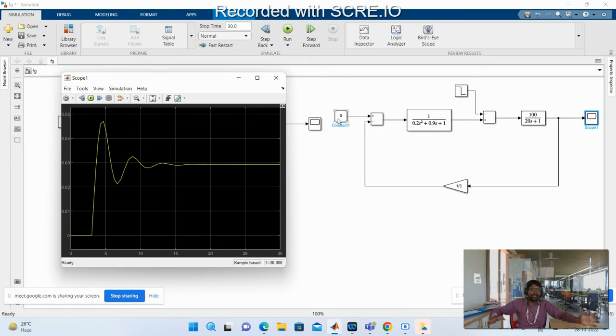The steam valve will be opened, more steam will go, then the generator speed will go up, and frequency increases and reaches the nominal value. So you have to control the speed changer position in such a way that even if the load varies, after a certain period of time your system regains its nominal frequency.